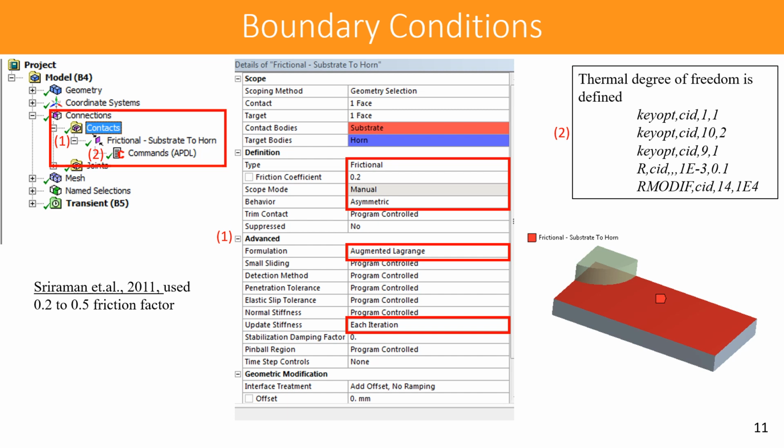It doesn't really have the temperature information, so I have to put that information in the user defined command, or the command window. I have to put this information, which I found in the ANSYS help again, that is defining the elements, and defining the condition at the interface and calling the nodes to implement the thermal condition.